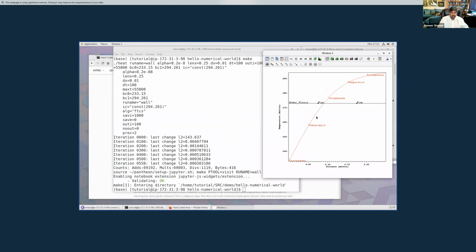And here is the chart that comes up. This is the 273 Kelvin at which the pipes will freeze. This line, and this is the distance in meters of how far the pipe is from the insulation. And at 0.15 meters, you can see that I am at this temperature, and the pipe is above the freezing temperature. And so the pipe will not freeze.